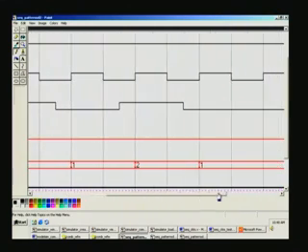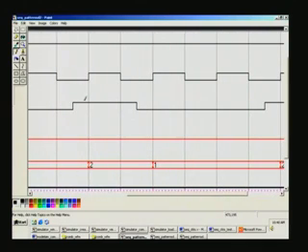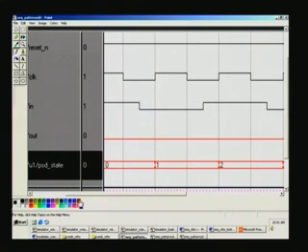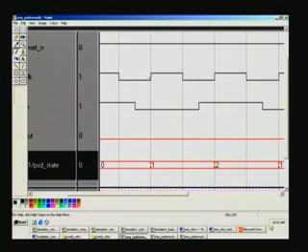So, now at 2 let us put the same condition. So, at 2 naturally it is not this one, but this, yes. Go back to the first beginning. At the positive edge of the clock, the input is 0. So, it goes to S1 state.